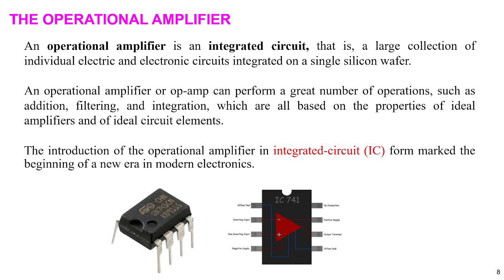And this is the practical op amp. Usually we use the IC number 741 as the op amp here. We have the inputs and the output here. With these two inputs, if we connect them with some source signal, we can get an output signal maybe larger, like this. But in practice, this type of device will need a power supply, right? We need a positive supply and a negative supply.